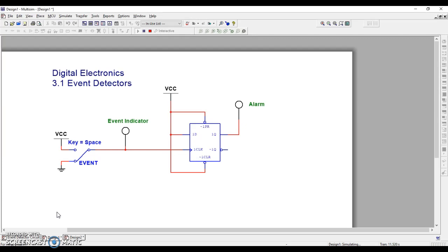So we went through the D flip-flop in our previous video series. If you haven't watched that, you probably need to go watch that. And basically the idea with the D flip-flop, it's an edge-triggered flip-flop, and what happens is this signal from D will pass through to Q. So if this is a 0, it'll pass the 0 through. If it's a 1, it'll pass a 1 through to Q. But it'll only occur when the external clock is positively edge-triggered.